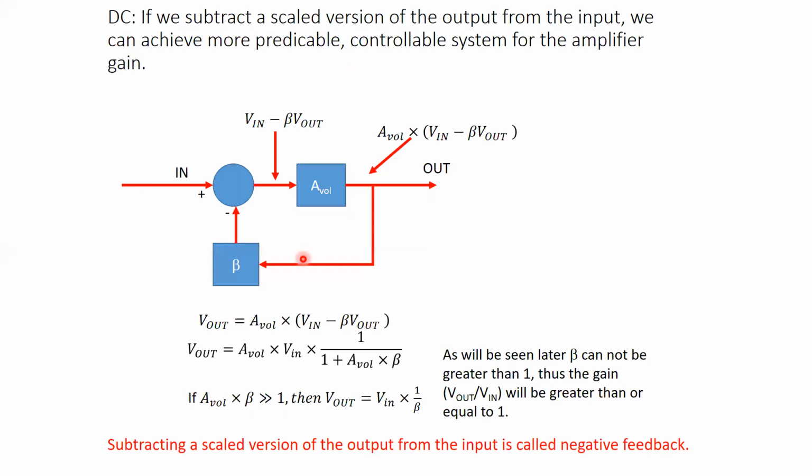Any questions on this so far? Because right now, what I'm telling you is that so far, we said the open loop gain as a function of frequency equaled infinity. That's been our model so far. And I'm telling you that's not true. The easiest model is open loop gain divided by S, so you just get that straight line.